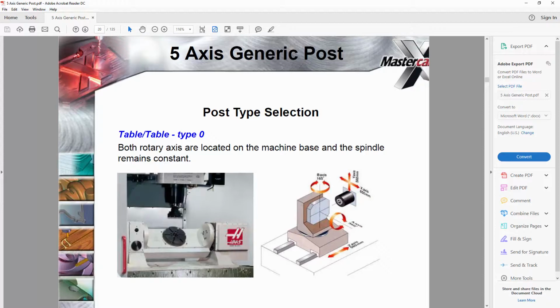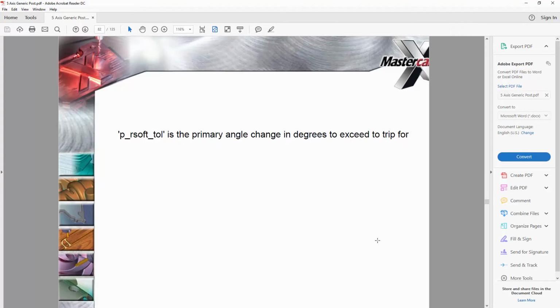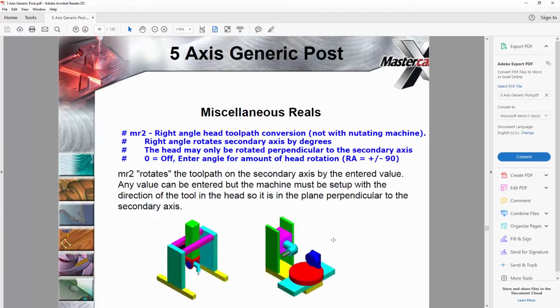So a lot of the times when you're programming, maybe your plane is flipped around, or the last position of the post is closer to the negative side, so your last toolpath went in the correct direction, but now your third toolpath or whatever forces the table to go to the opposite side. And in those cases, this switch is useful for limiting or eliminating that behavior.